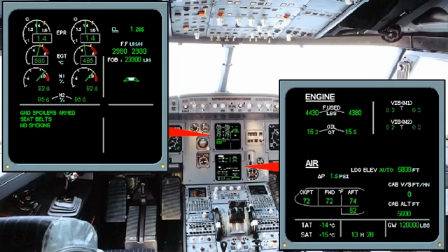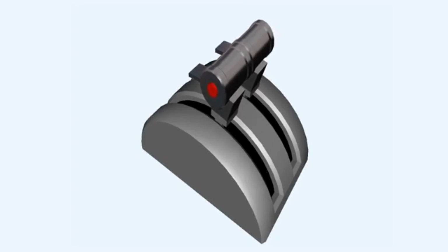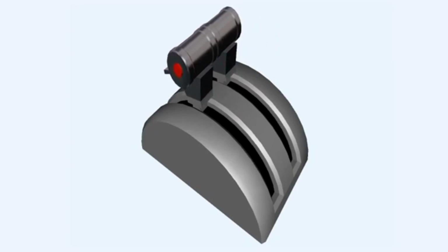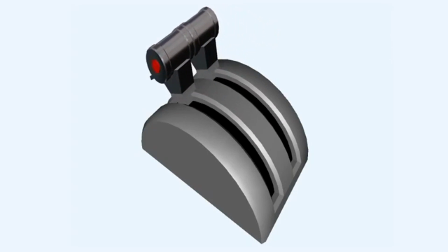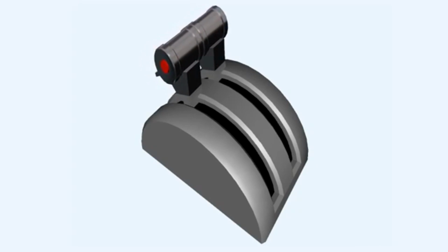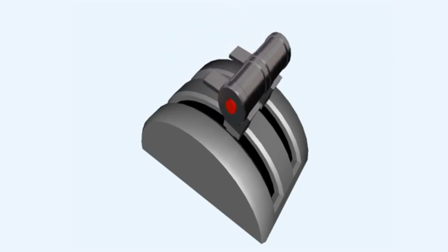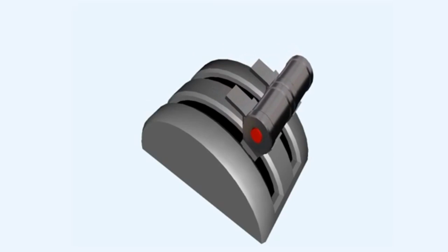Apart from the loud noise that usually accompanies a surge, there is a large rise in the EGT, and the resulting loss of thrust may cause the aircraft to yaw. The pilot must always be conscious of the causes of stall or surge if he is to prevent either from occurring. Smooth operation of the throttles, both when advancing and retarding them, will ensure reliable and prompt response from the engine. The pilot must also be very aware of the restrictions which RPM and the ambient density place upon the power plant, and amend engine handling accordingly.